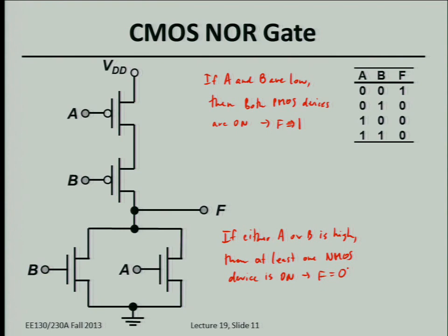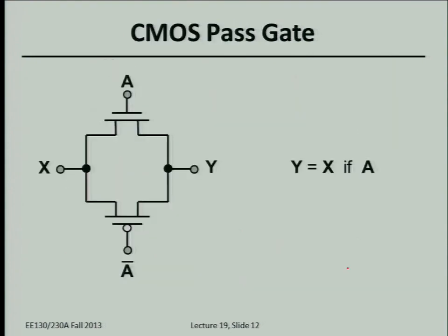Okay, so this is how CMOS logic devices work. When a transistor is off, it's supposed to not conduct current under large drain to source voltage. When a device is on, it's supposed to connect the output to ground with as little resistance as possible. That's the ideal case. That's what we mean when the on current is high. That means the effective resistance of your MOSFET inversion layer channel is low. Okay, any questions about operation of NMOS and PMOS?